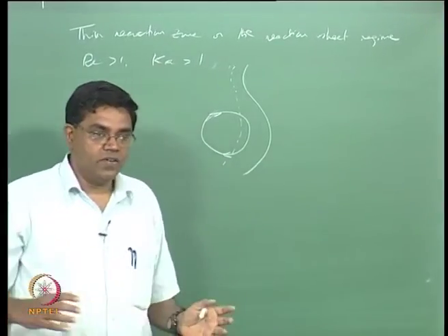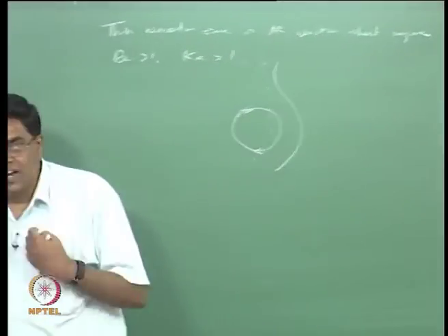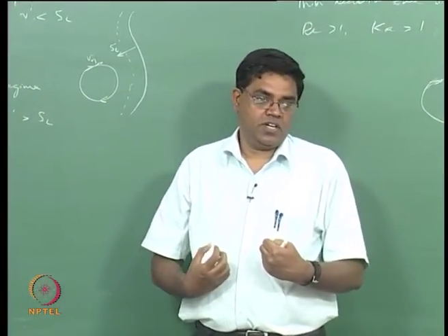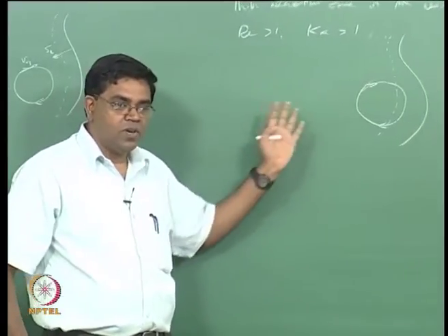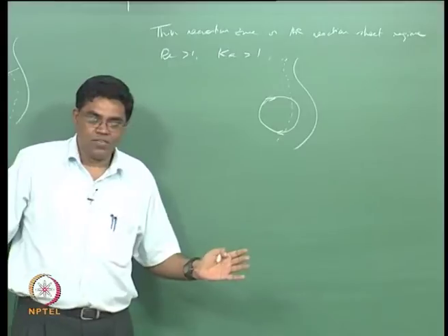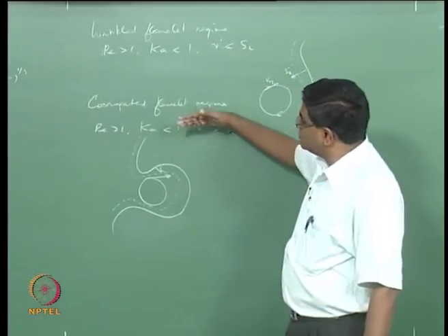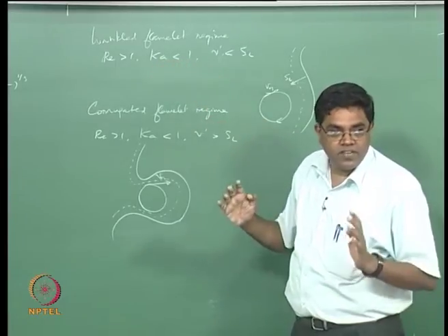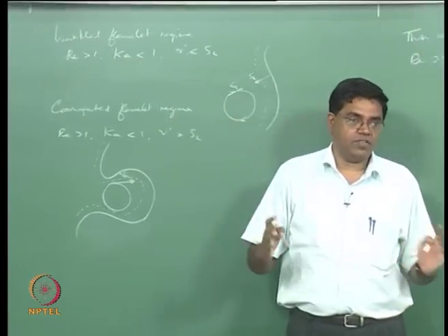So effectively the way we are thinking about this is, can I hold on to my laminar knowledge, right, and that's just beginning to get breached here by the turbulence. Until then it's okay, right. And there's a reason why we have been using this term called flamelet all the time, and there is this basic idea of what's called laminar flamelets.